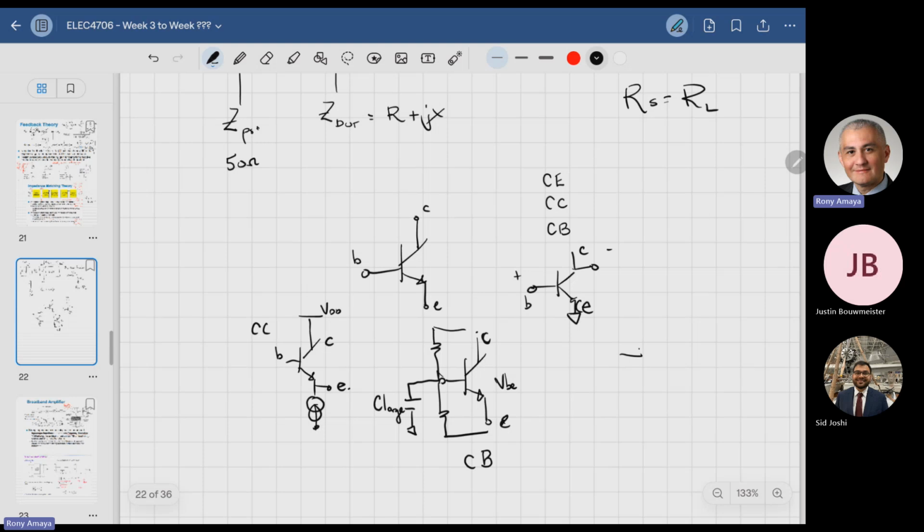Because a capacitor at DC behaves like what? DC: open, right? And at AC, sorry, I heard the opposite. It's a short. So AC wise, effectively short that node, and now it's a 2-port device.